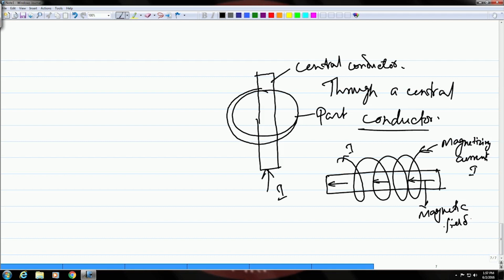So, the flaws and defects which are perpendicular to the axis of the part, or perpendicular to this longitudinal direction, will have the best visibility. Okay. And if you have cracks at angles, let us say 45-degree angles like this, then also this kind of cracks would be visible.